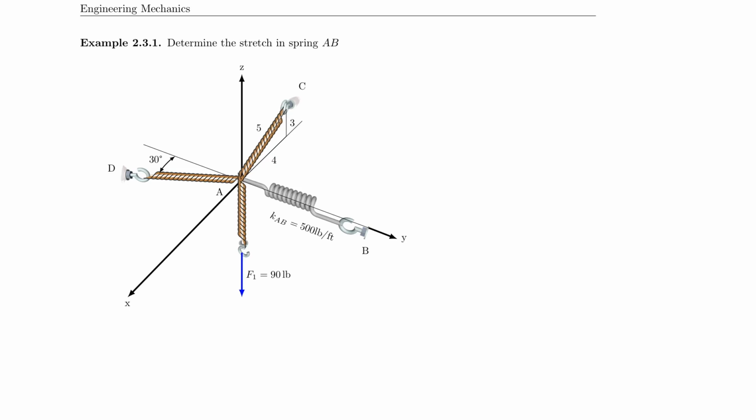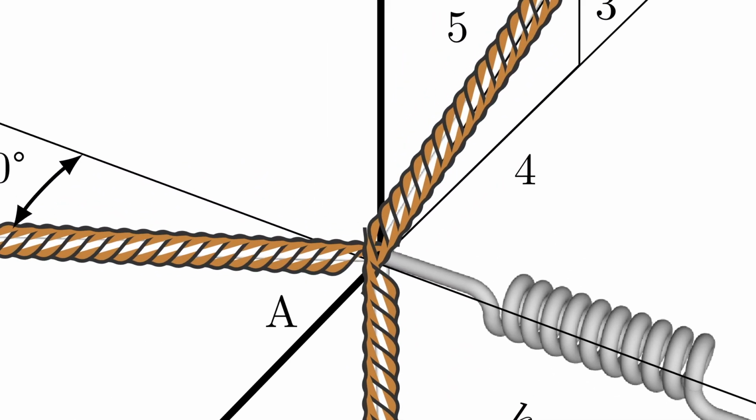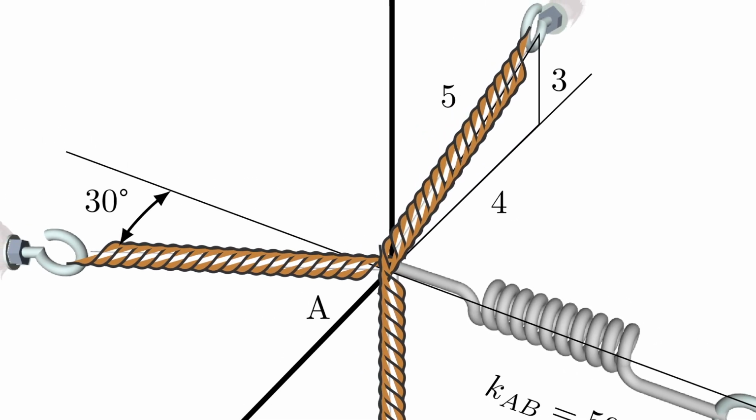Maybe the first thing I'm going to do is superimpose a little free body diagram. Since I can zoom in here and make sure that we understand that it's really acting at this node, I'm going to draw the free body diagram for node A here. What I will find is that I have forces in all 3 directions, but differently distributed over the cables.